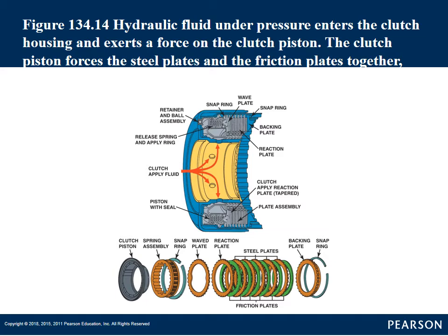If I have much bigger clutch discs, but only 3 or 4, that might hold just as much as a smaller diameter clutch pack that has 6 clutch discs in it, because we're still getting about the same amount of surface area. In most cases, this is not adjustable, how many clutches you put in a clutch pack.